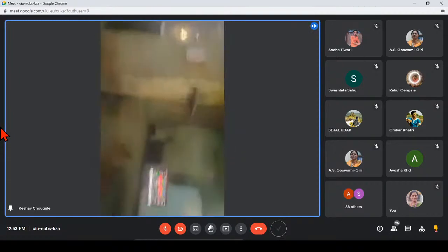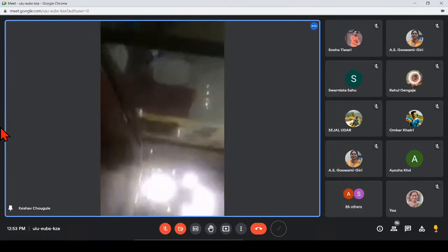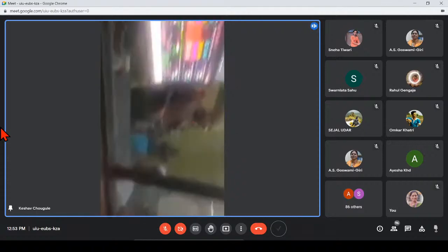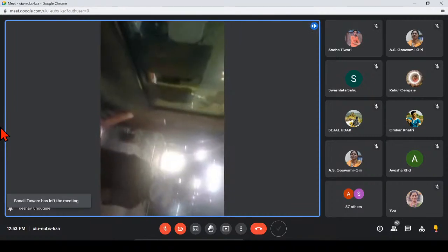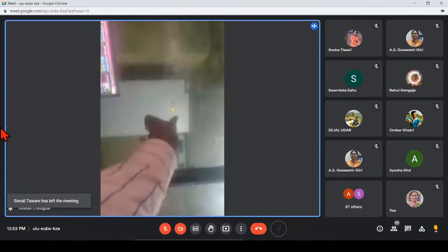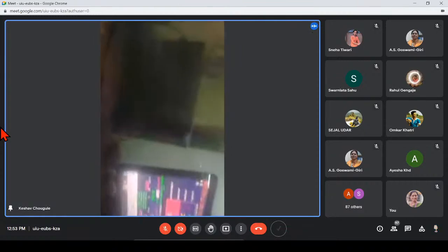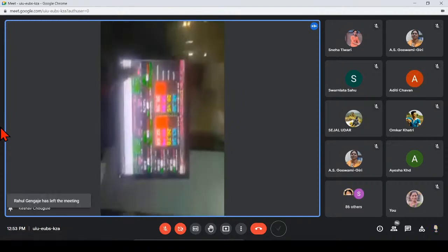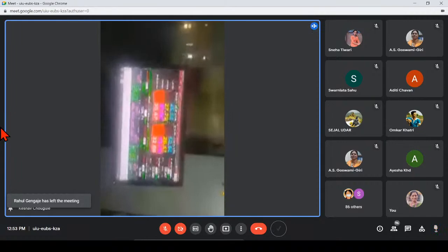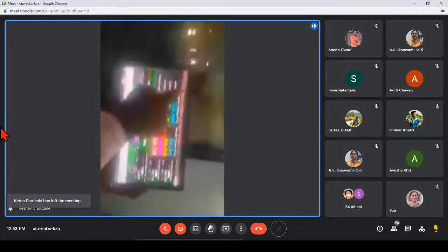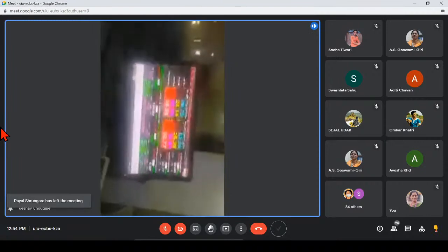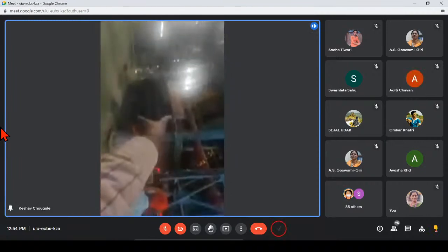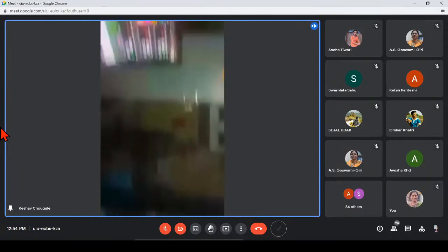On the upper side of the boiler there are some sensors and control valves. Whatever readings are sensed by the sensors and control valves are all displayed on the screen. See, this is the screen. All the connections of the sensors and control valves are given to the PLC control panel, and the PLC control panel connections are given to the screen. See, there is steam, water, pressure and level. There are different levels of steam and water coming into the boiler, as well as pressure in the boiler, for boiler number 1 and another for boiler number 2. There are two boilers used in the sugar factory. This is the boiler number 1 reading for this boiling section.